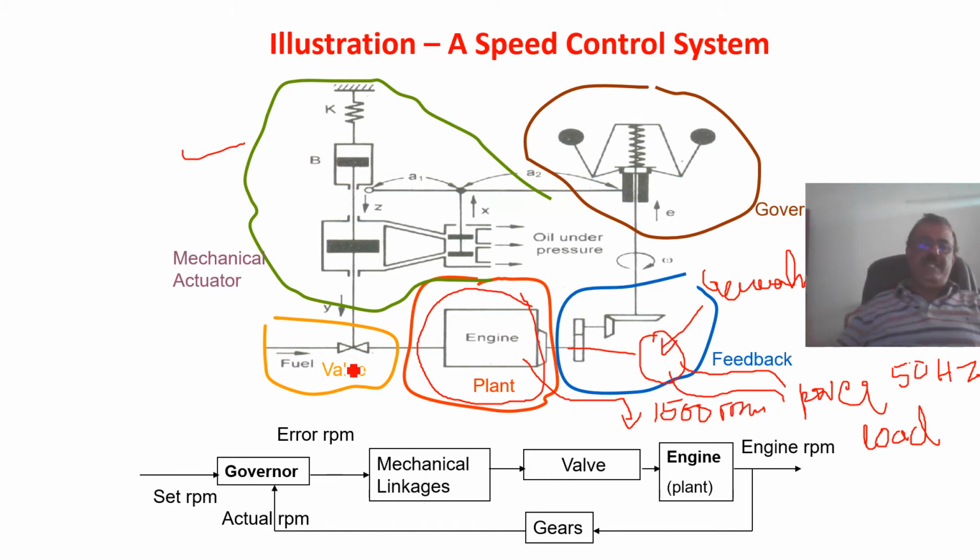To get this speed, I adjust the fuel valve, say by adjusting the governor's flyball positions. This is what you call the governor. You can see here that at this position of the governor, this linkage and the valve, all these linkages, are at particular defined positions so that the fuel is flowing and the engine is running at that speed.